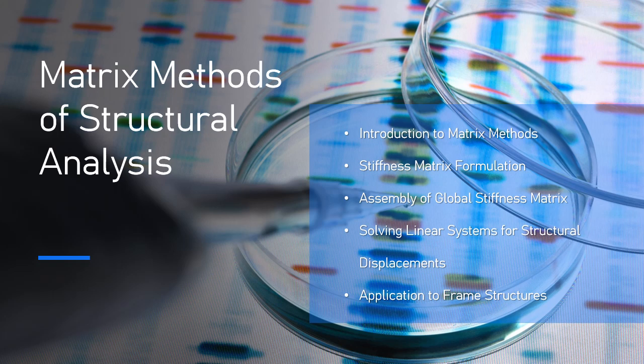5. Solve the system of equations. Solve the matrix equation KΔ = F to find the displacements at each degree of freedom. 6. Calculate internal forces. Once the displacements are determined, use the stiffness matrix to calculate the internal forces and moments in the structure, such as bending moments, shear forces, and axial forces.